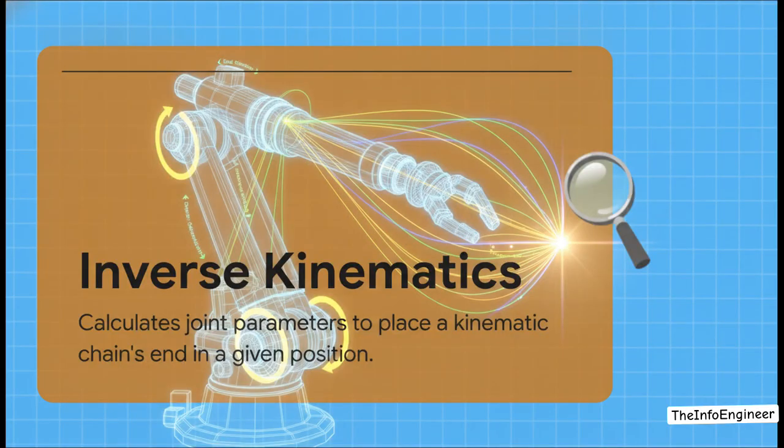This is where inverse kinematics, or IK, comes into play. If you want to move the end effector, which is just the technical name for the hand or tool at the end of the arm, to a specific point, IK calculates the geometry for the shoulder, elbow, and wrist all at once. You dictate the 3D destination, and the IK engine actually reverses the math to figure out exactly how much each specific joint needs to rotate across 6 independent axes or degrees of freedom to make that happen.